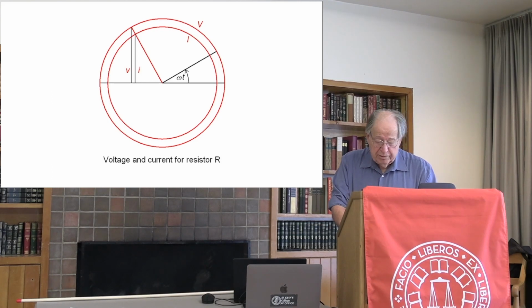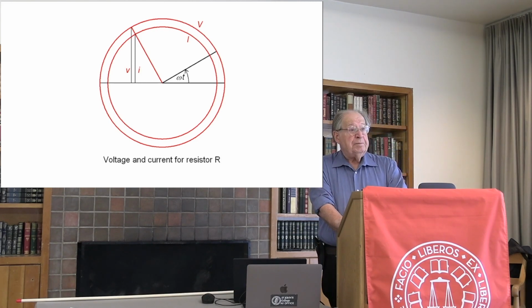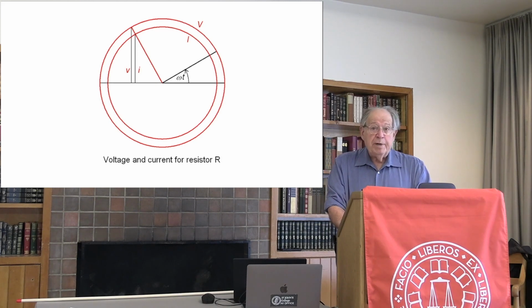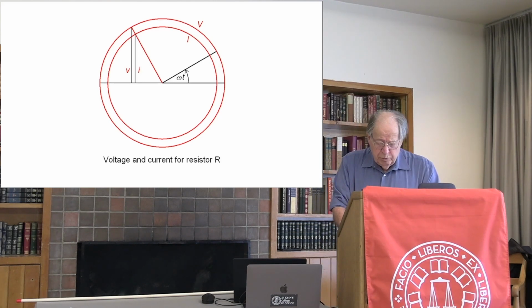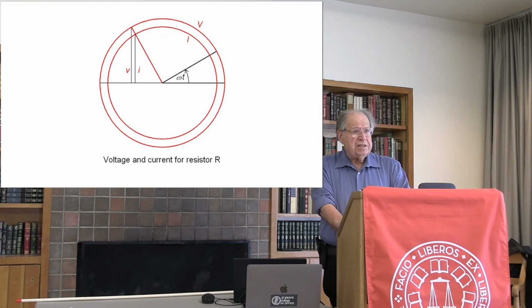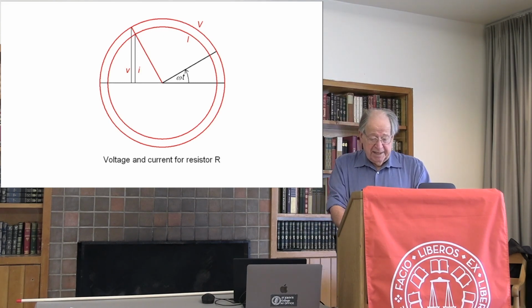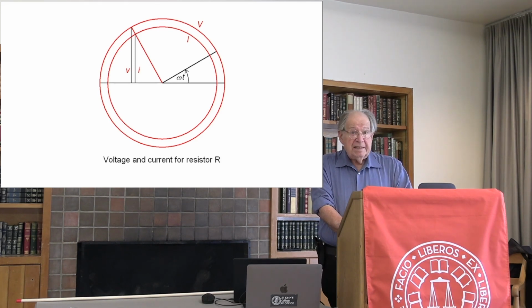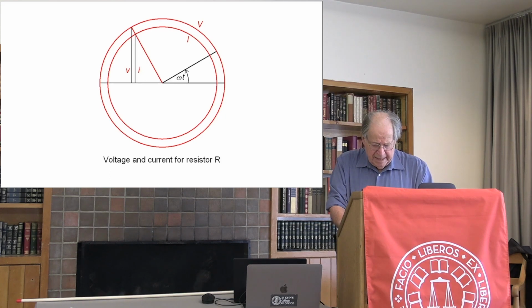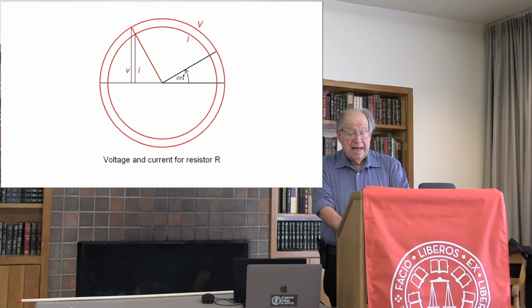But voltage and current are synchronous only for the property called resistance, and we can now distinguish rigorously between that property and the properties of inductance and capacitance, which belong not to conductors as such, but to the magnetic and electric fields that accompany the currents they carry. Evidently, those properties were always present, and indeed must exist to some degree in every electrical circuit. But we never noticed them until alternating current made them manifest.